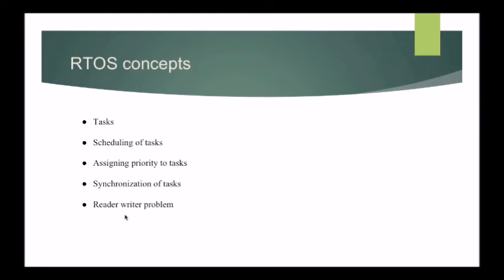In this project, each functionality has been done as a separate task. Each task could be given a priority, starting from 0 to a maximum priority. The scheduler ensures that the task in the ready or running state will always be given the processor. So the one with the high priority will be given the processor first, rather than one which has a very low priority.